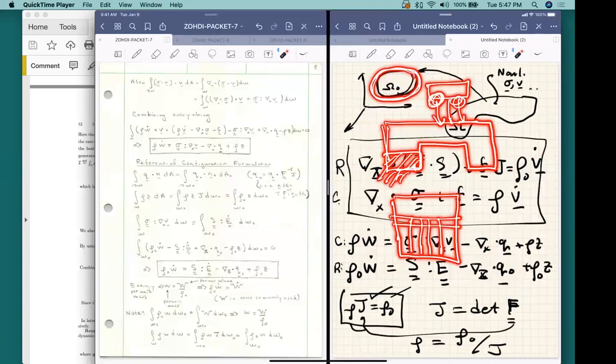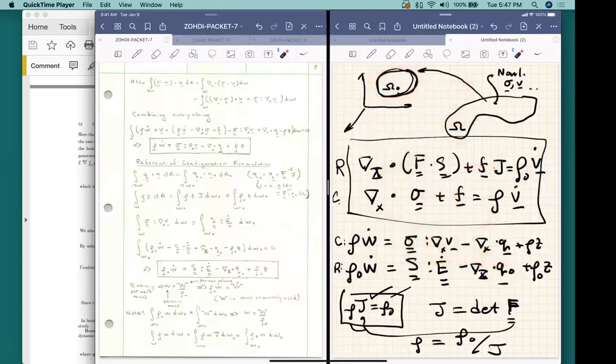If you're worried about a fire or some other thing in the system and the struts start to get hot and soft, they can easily buckle if a load is applied to them if the material is hotter. So this equation was the one that came to the rescue. It was used day in and day out to figure out whether we were going to have thermomechanical buckling and failure of that sort.